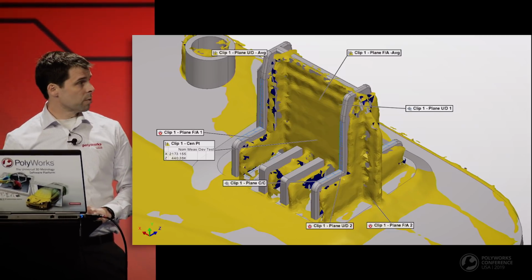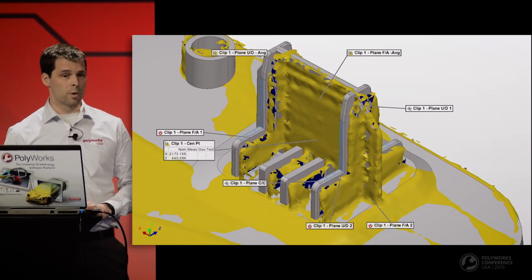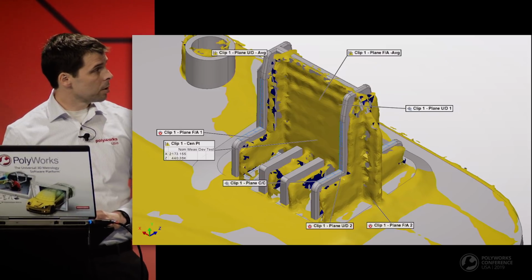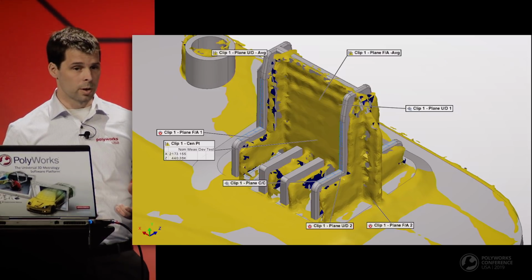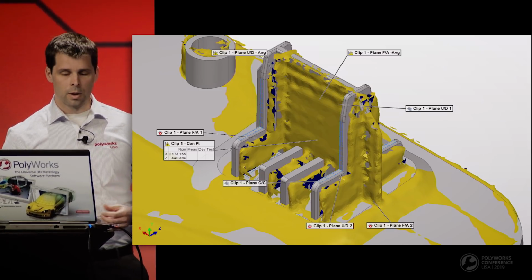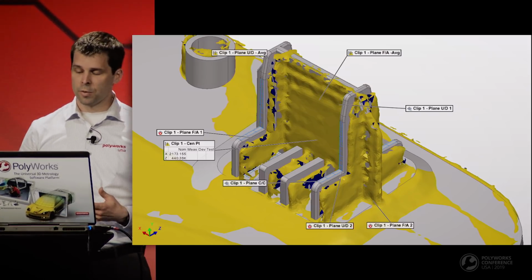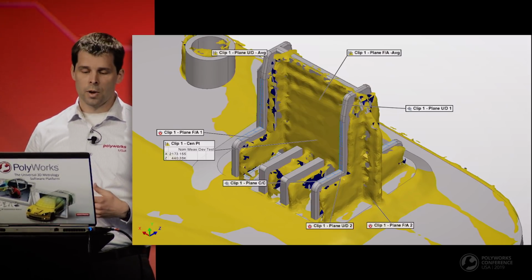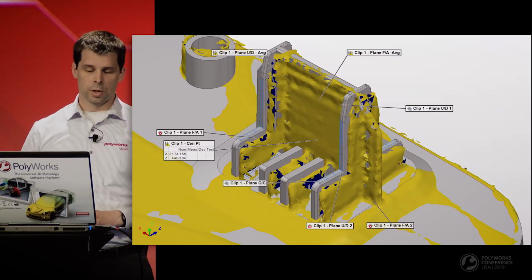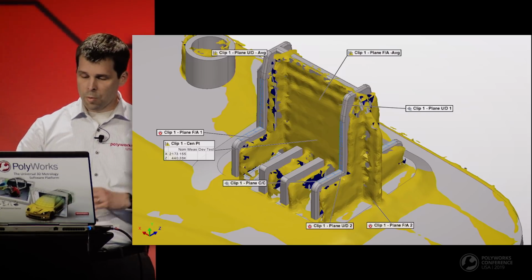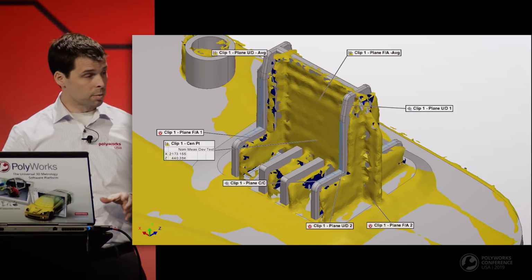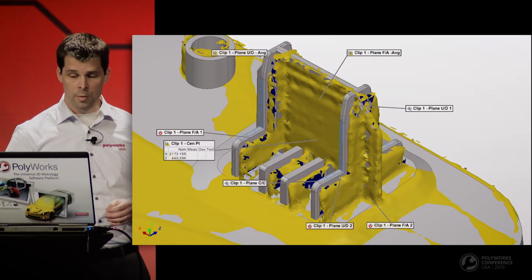The planes are very small, and with surfaces this small, extractions can become an issue. And if one plane fails to extract, we can no longer report the dependent center point. So in production, we end up spending a significant amount of time troubleshooting extraction parameters. Probing is not an option due to the small size of the planes and other process requirements.